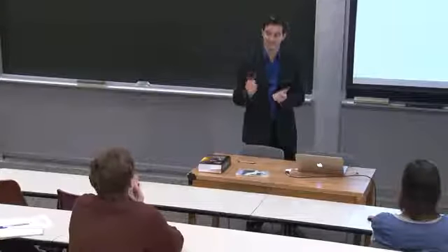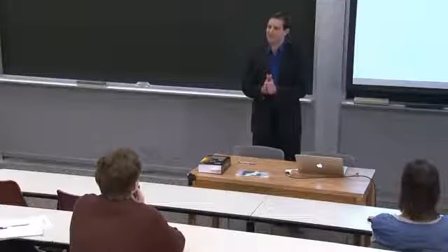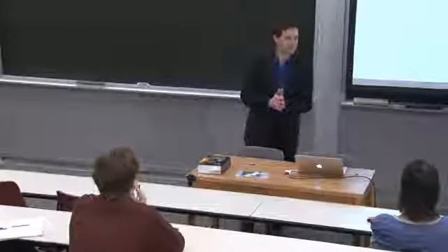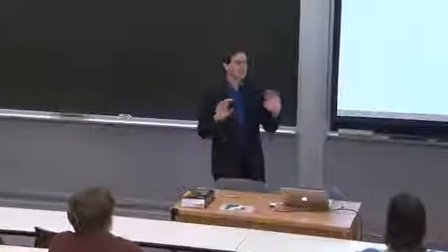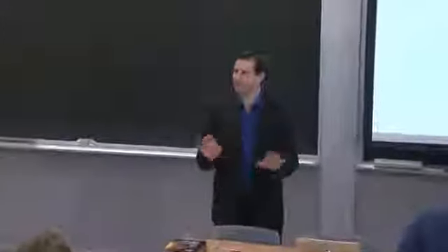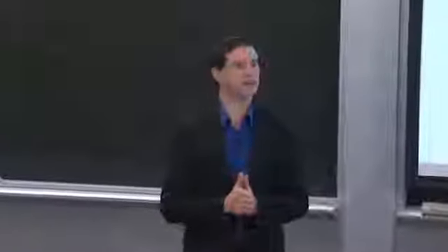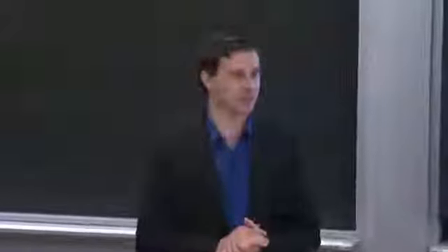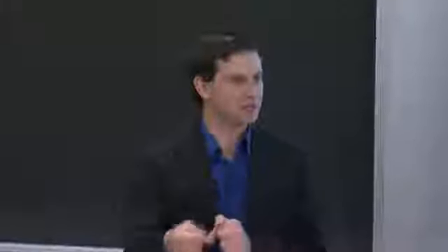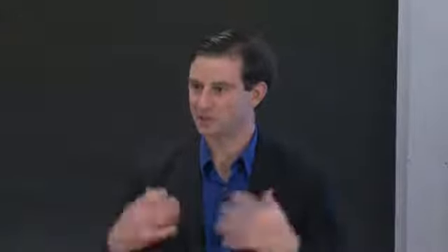I see. Okay. So did anybody else pick up on the point at the very beginning of his presentation? He said a p-n junction isn't necessary to separate charge. Okay, that's fine. We've talked about heterojunctions. We all agree. There are other ways to separate charge. And he said an electric field is not necessary to separate charge. But then he immediately went into discussing how the chemical potential was slightly lower in the contact than it was in the semiconductor, which would result in a charge imbalance, which would result in a field.